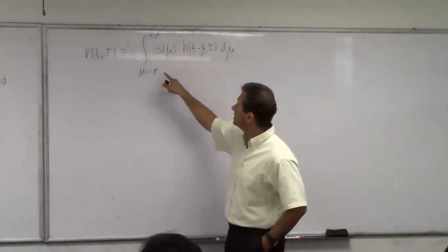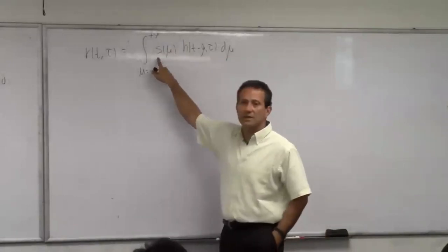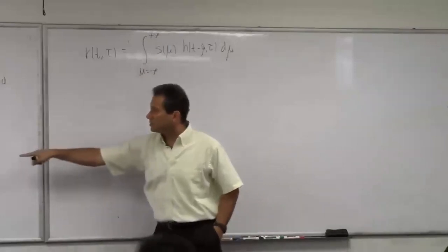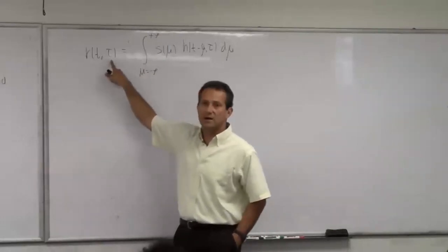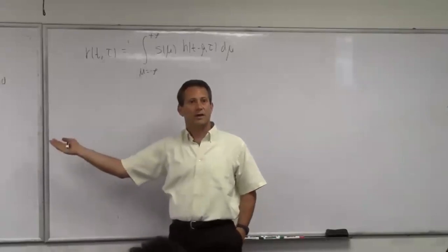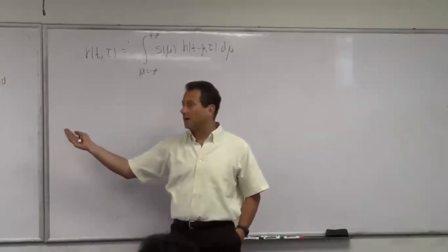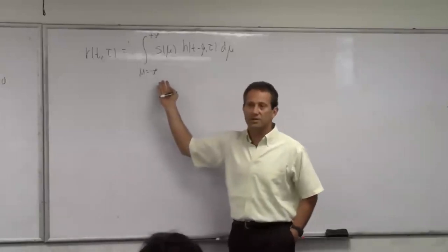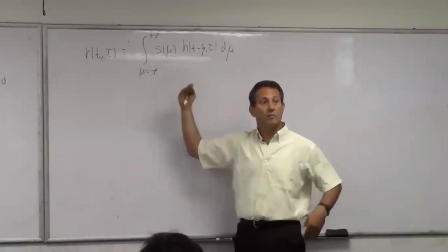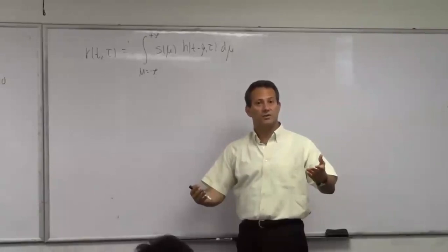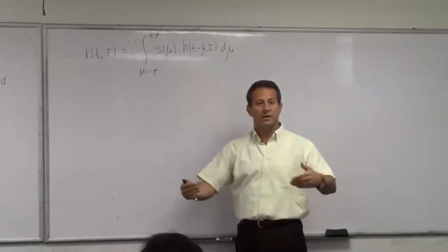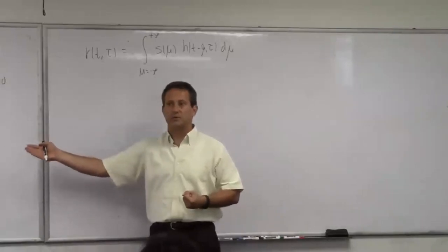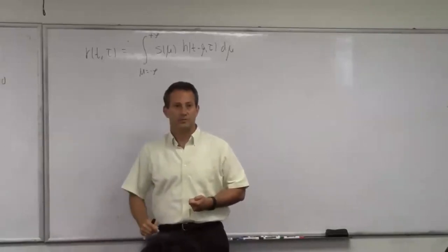Here, what you have embedded is that if I take the same signal, S of t, and feed it into this channel at two different times, tau, I'm going to get different output. The input-output relationship is still linear, still convolution, but the impulse response of the channel changes over time. Therefore, even the same input fed at two different times will give me different output.